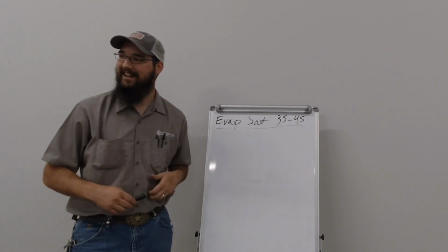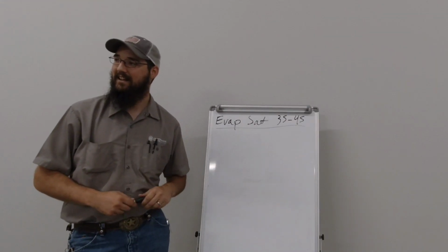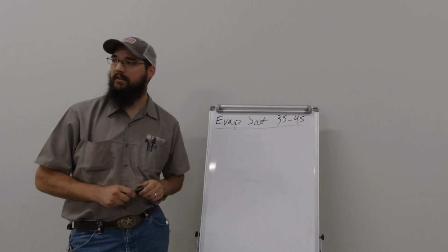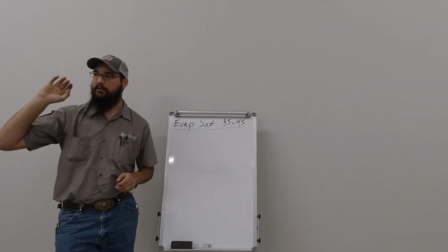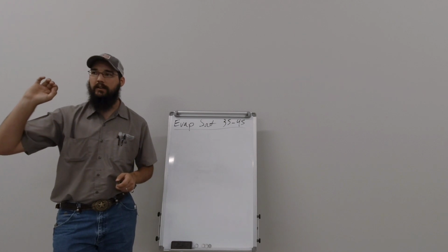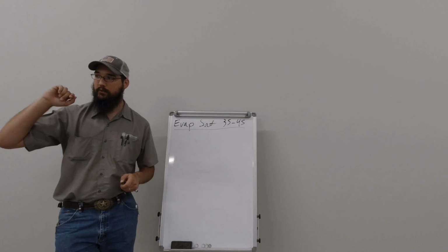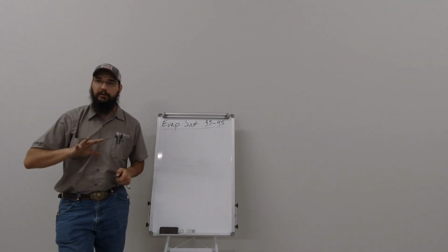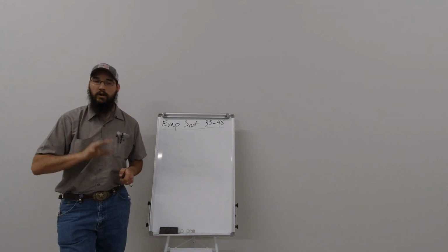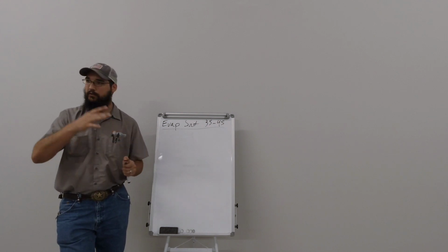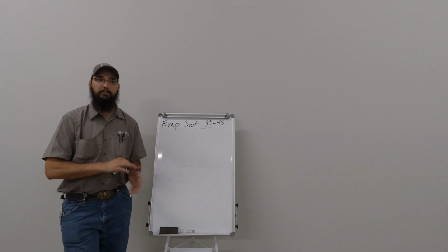When you click on refrigerant, it doesn't allow you to change that. On 407C, it does allow. Yep. 410A, it does also allow you to change. The blends are the ones that are going to get you for that. If you look, 404A also has it. The 400 series refrigerants, if you don't know, are your blends. So if it's got a 4 in front of all those numbers, that is a blend, period.